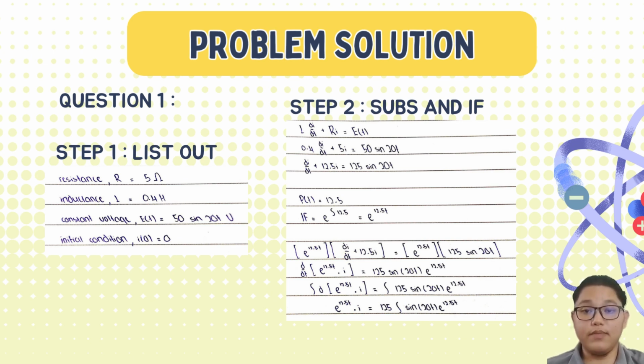The next step is to find the integrating factor, IF, which equals e^(12.5t). The next step is to multiply the integrating factor with both sides. After that, we can simplify it, and we get the simplified version, which is e^(12.5t) I equals the integral of 125 sin 20t e^(12.5t).